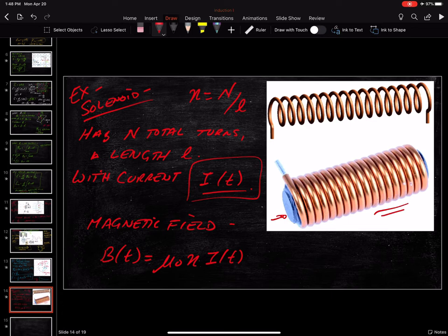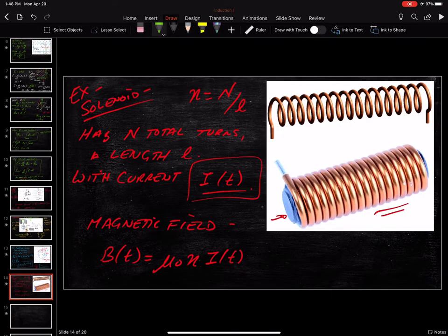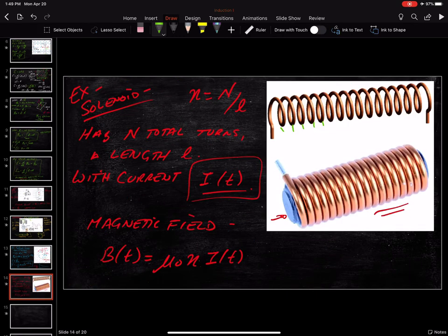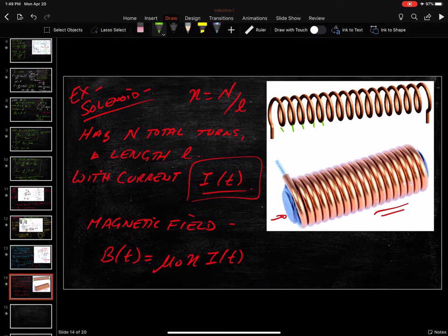Well, we got to be a little bit careful. If I want to think about the magnetic flux, through which loop? There's a magnetic flux through each of these loops. And every time you go through each of these loops, you create a little voltage in each of the loops. Okay? And so basically you're stacking up one of these loops here on top of the next, on top of the next, on top of the next. And so the more loops you have, the more voltage you induce. And so this is a sneaky way of sort of cheating nature to get more energy. Okay? You want more energy from a given magnetic field, just loop more wires around. Okay? And so that's pretty cool.